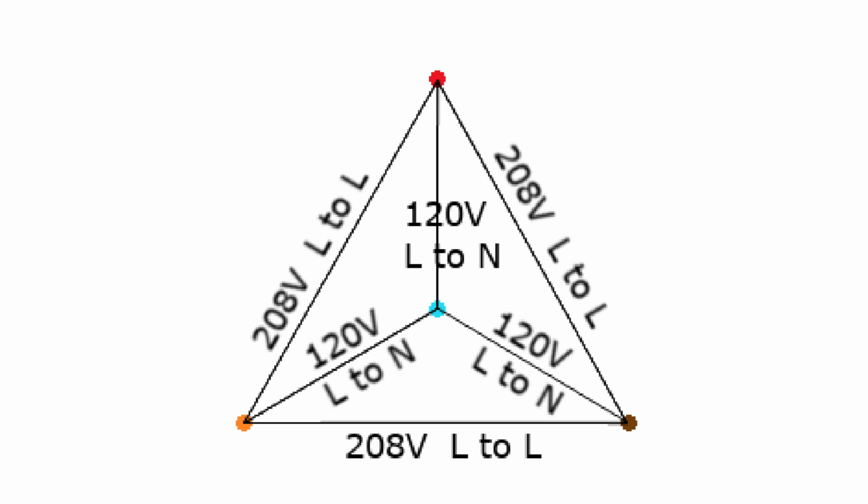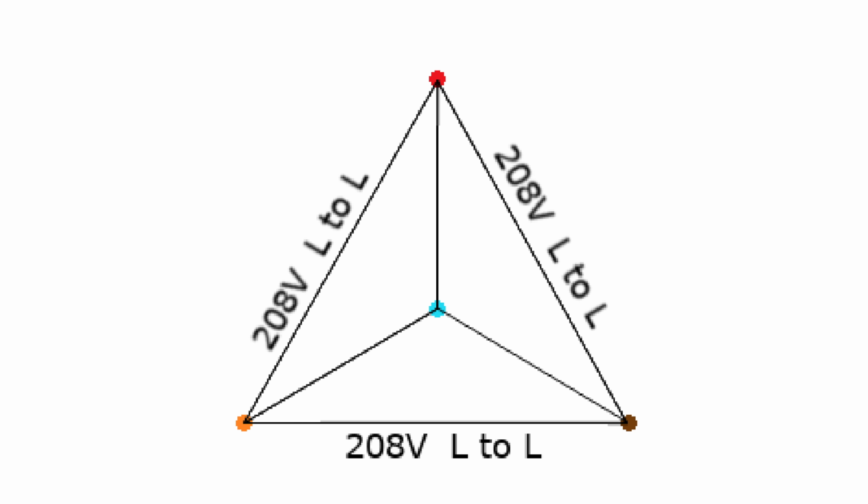Now, a three-phase delta system is exactly the same, except we don't have a neutral. Now, when I say that, I mean a standard three-phase delta system, such as a 480 three-phase delta, where there is no neutral at all. There is a three-phase delta system that is called high leg or stinger leg that we will be discussing, and that is an exception. That does have a neutral in it. But with a standard three-phase delta, it's just like this with no neutral, and often the voltages will be different, whether it be 480 or something like that.